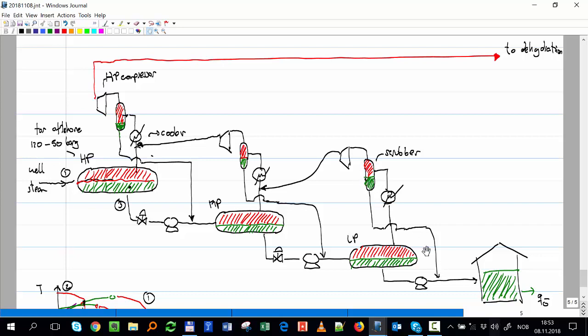From here? Yes. Well, that's a very low pressure, but the pressure of that line should always be a bit less than the pressure of... okay, when you go from here to here, this pump has a very low pressure drop. It's just to carry the fluid from this separator all the way to the low pressure. But this pressure is still lower than this pressure, because it's gas, it doesn't lose pressure so much, okay? So this pressure is closer to the medium pressure, and therefore is still bigger than the lower pressure, and therefore you always have fluid on that.